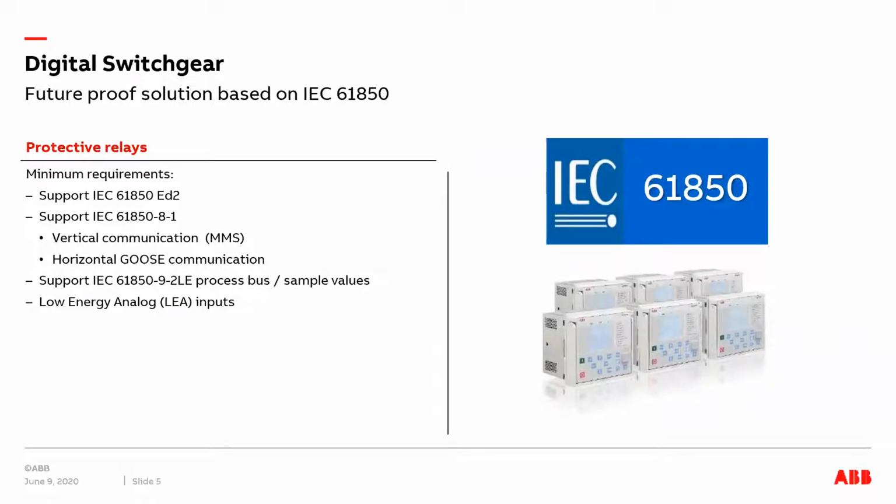It should support IEC 61850-8-1, which is the station bus standard, which involves vertical communication, MMS, which we mentioned, and also GOOSE communication, which is horizontal communication. And it should also support 61850-9-2 LE process bus, or the sample values, as we mentioned.